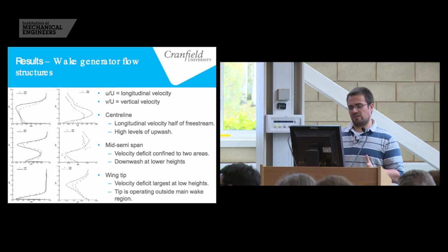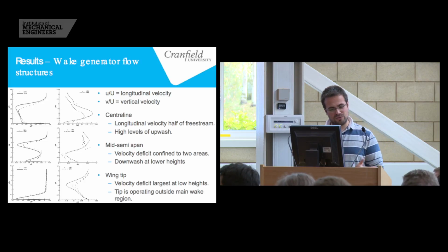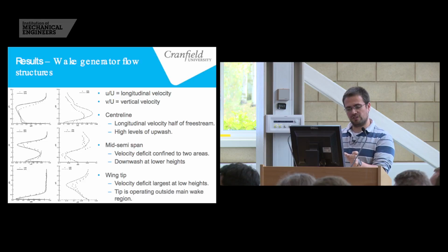So, validating the LDA with the CFD, although the velocity profiles do not match up perfectly, the trends are there. The forces match up perfectly, the flow on the wing matches up perfectly, but the wake itself does not match up perfectly, but I was stuck with it. On the left-hand side, we have the longitudinal velocities, and on the right-hand side, the vertical velocity component.